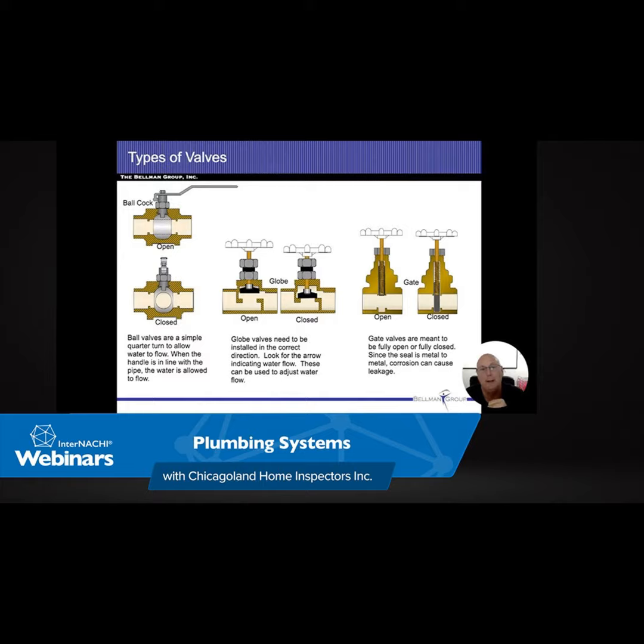Those are pretty much most of the metals that we deal with that are going to be an issue. None of those can touch each other. All right, there might be more, but none of those could touch each other. Now, there's also brass that gets used a lot in plumbing systems. Brass is the only metal that could touch any one of those. So brass is a natural dielectric union.